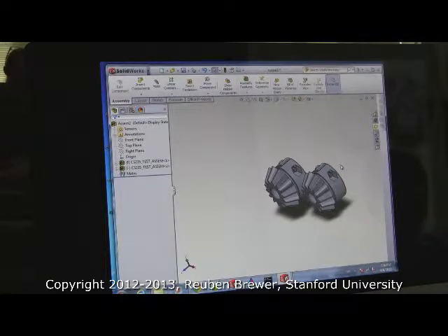So you want to make intelligent choices. If it's one of a kind, it's fine, just throw the parts into the master assembly. If you're ever copying it, make a sub-assembly. It'll save you a lot of time and effort.